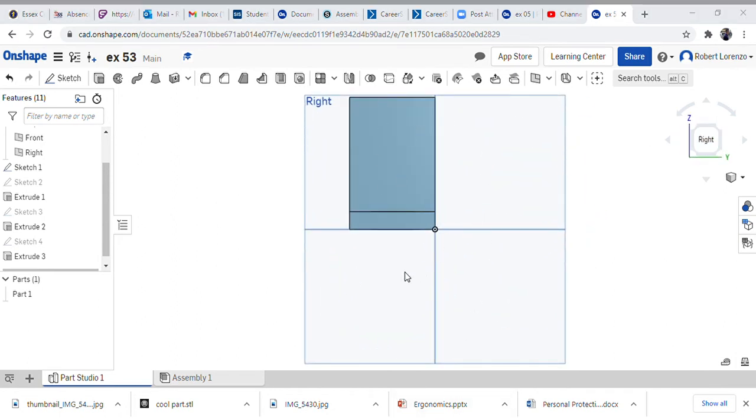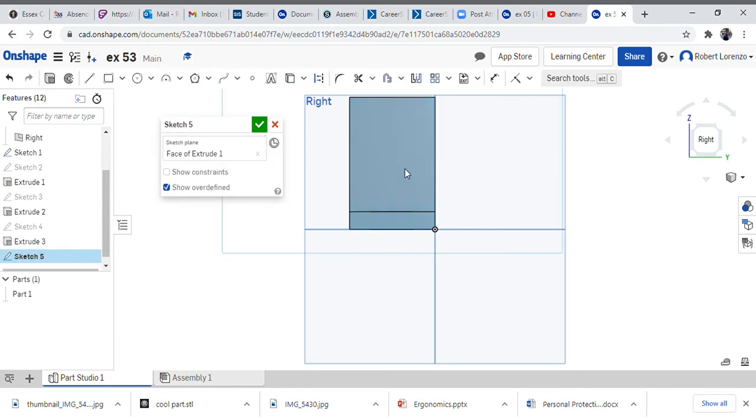Take a look at our picture. Again, that hole is a diameter of 25. This one's 50 from the bottom. And again, it's going to have to be, because of this radius, 25 in. So I'm not starting from the bottom, I'm starting from essentially this corner here. So I only have to go up 40. I'm subtracting this 10. So again, just like the other circles, I'm just trying to talk you through the entire process of how I come up with these numbers. I know that's sometimes a point of confusion for students.